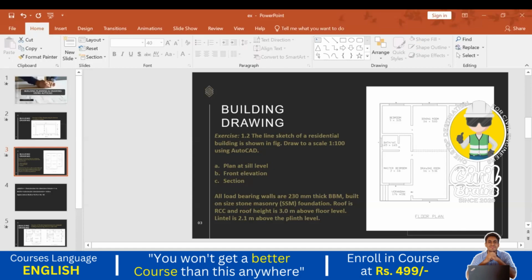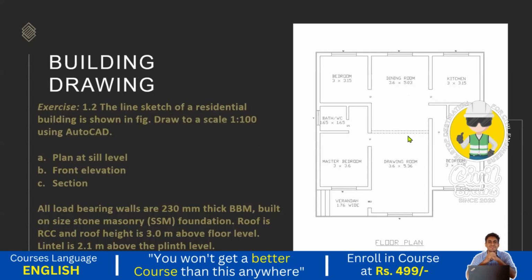What is the dimension of the dining room? 15.03. Here you can see there is a dotted line. So what is meant by a dotted line and what is meant by a solid line? Correct? If it is a dotted line in the plan, it means that there is no fixed wall, or there is no fixed structure. Always remember, if it is a straight solid line, then it means that there is a fixed